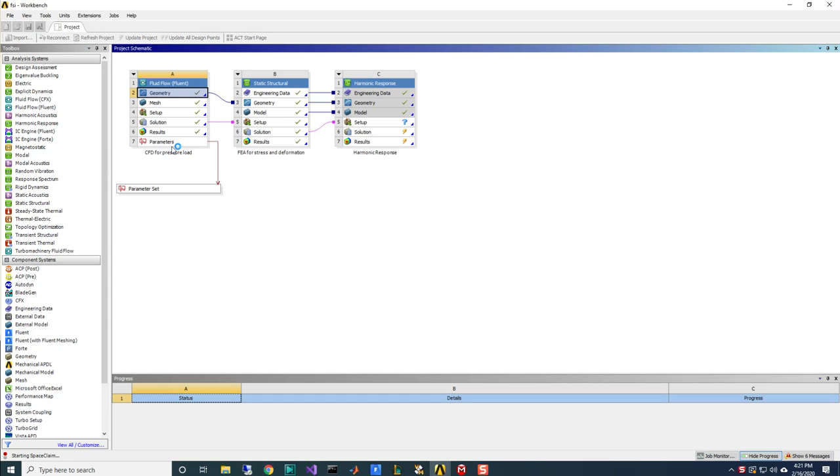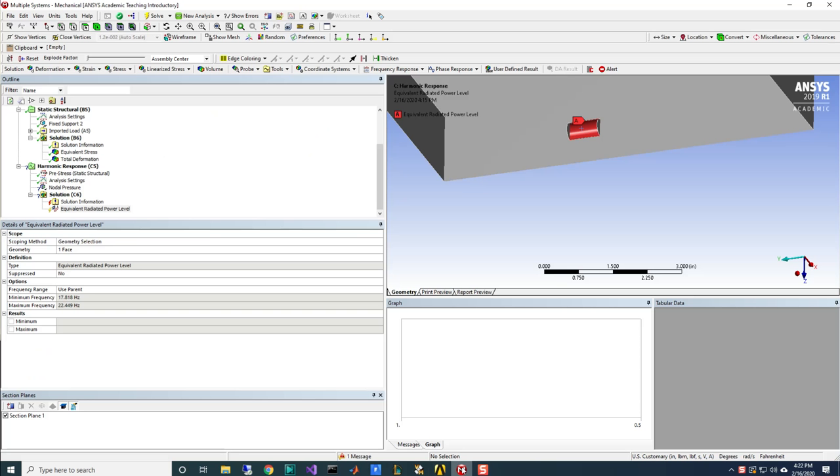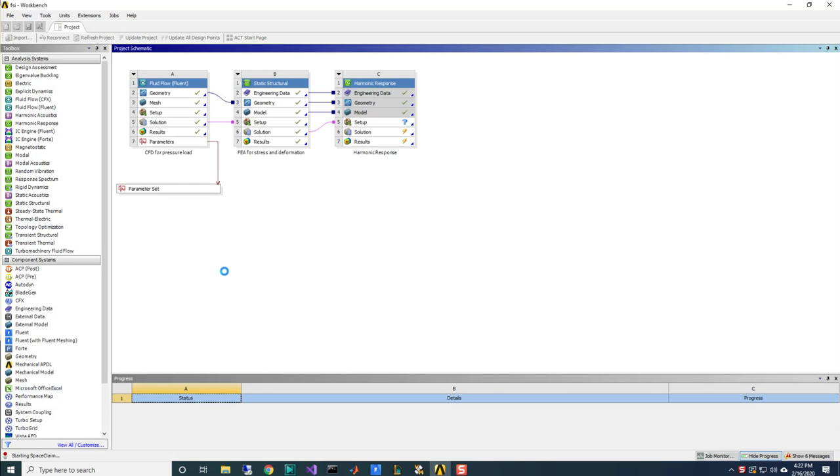Generate a mesh. That will be adequate. You can turn on thick shells and beams here and get an idea of what our tube looks like. I'm going to set up my structural calculation. I'm just going to grab the edges at both ends and fix them in place.